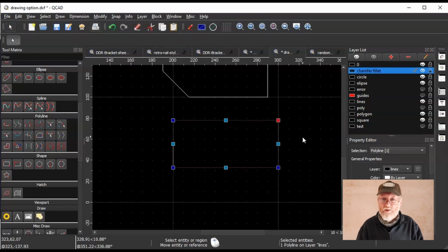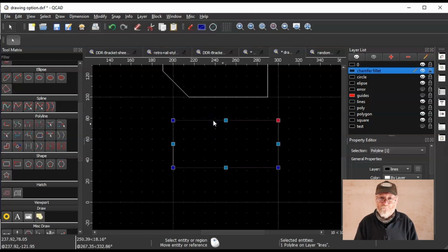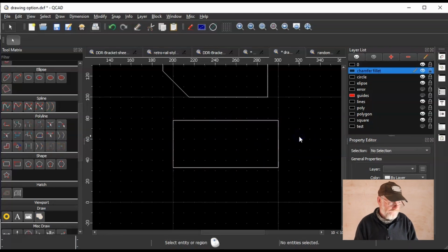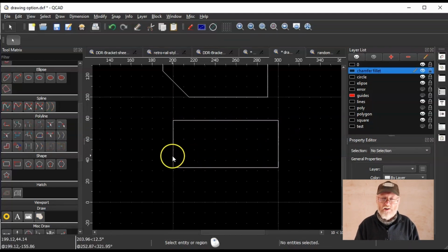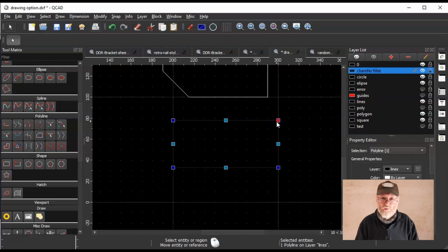In order to get this to work within CAM software, I would need to tell my software to define or enclose it, and so I would make a full segment from a polyline with a click of a button. Bit of a pain. I could have done it just as fast using a rectangle tool. But worse, it now hides an anomaly. Within that rectangle an extra line appears down here. You can't see it till you click on it, but that is enough to throw out the CAM software.